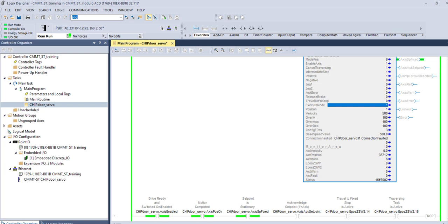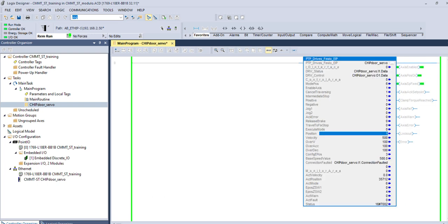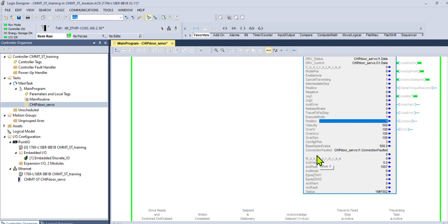So I change it to 0, and I change it to 1. And now you can see that we have the green on the axis reference. It went to our record table and did the sequence, and the actual value is 10 degrees right now. So we did use the record table to home it, set modulo, and then bump it off 10 degrees. So everything worked as planned.